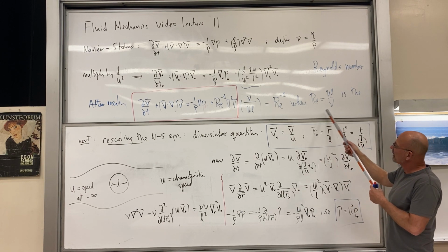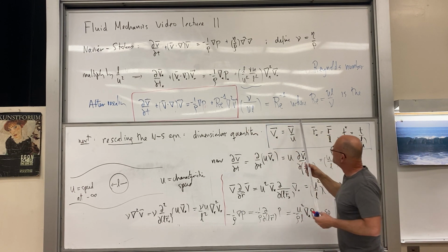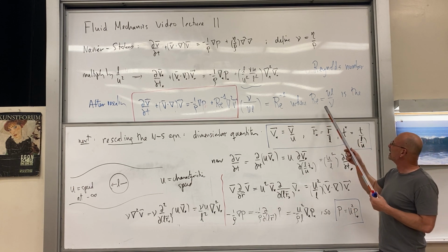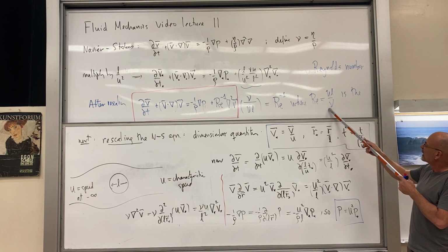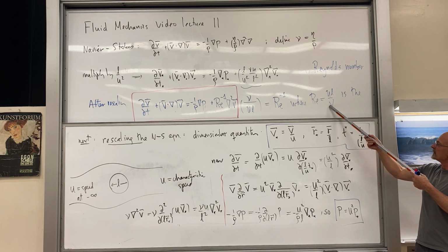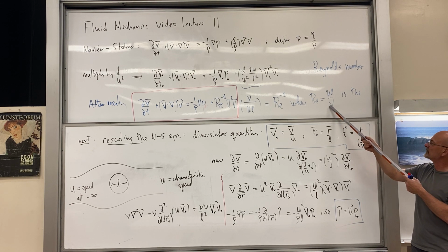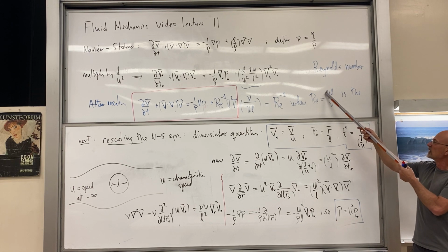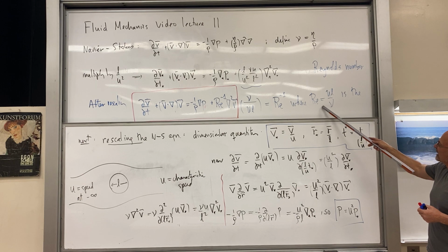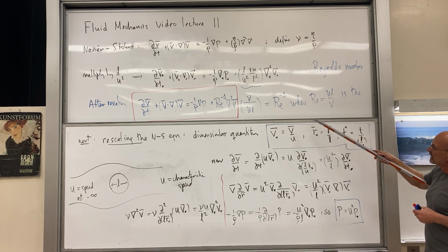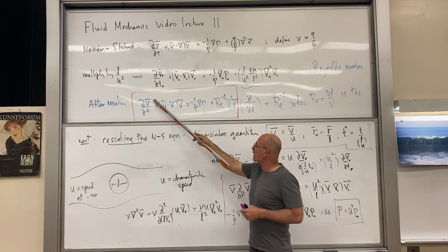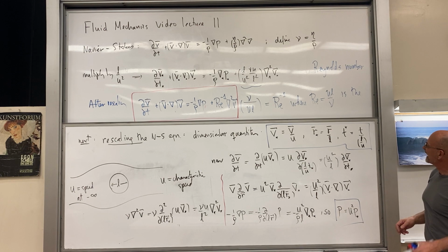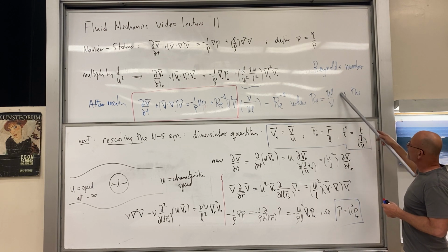We've got this Reynolds number to the minus 1. So the Reynolds number goes towards infinity when the viscosity goes towards 0. And of course it goes to infinity if the dimensions and the speeds grow. But what we say is, in the limit as the Reynolds number goes to infinity, we would get back the Euler equation. But this combination is universal in the following sense.